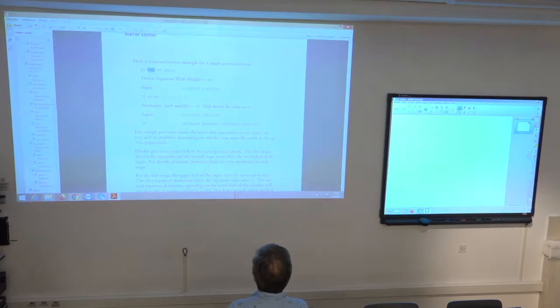If there is no argument for by how many bit positions I perform the shifting, then it means that it comes from this SE register. So this SE holds the value. It says here SE was previously set to -3, and then it means this instruction will perform a right shift by 3 positions.